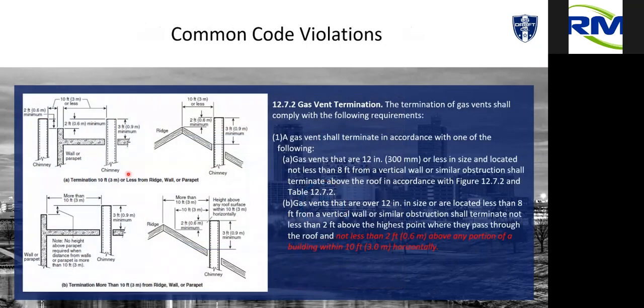So why would you use mechanical draft? Well, we showed you a few applications where the manufacturer just doesn't allow it. If you can't common vent that boiler naturally through the manufacturer's requirements, then you need a mechanical draft. But there are also other instances where the vent is fully within the manufacturer's allotment and it fully functions under design, but we have some code violations.